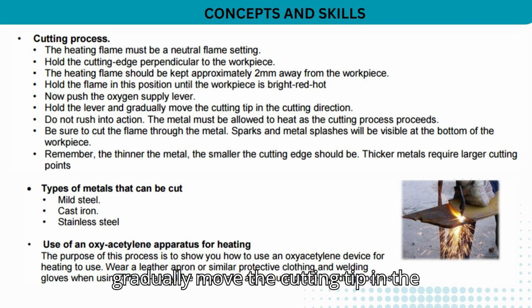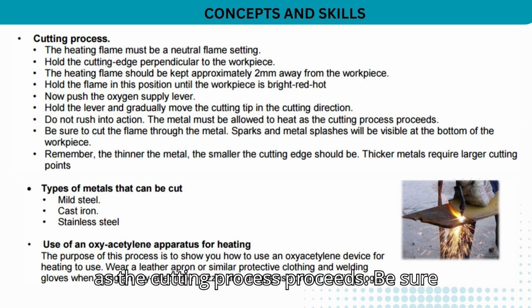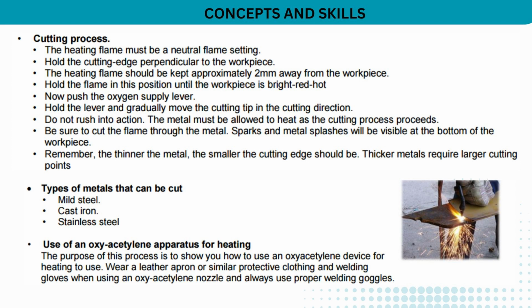Hold the lever and gradually move the cutting tip in the cutting direction. Do not rush into action. The metal must be allowed to heat as the cutting process proceeds. Be sure to cut the flame through the metal. Sparks and metal splashes will be visible at the bottom of the workpiece.